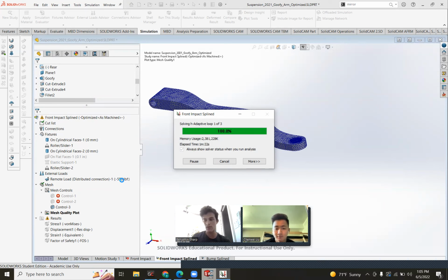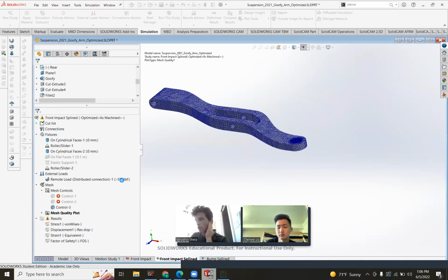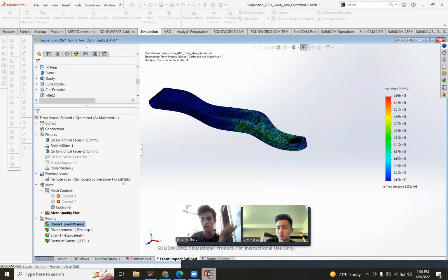Well, the reason it does not matter whether SolidWorks tells you there's like 1 or 2 failing elements in the bearing cup is because there's just a lot of tiny edges in there, but also because it tells us that the bearing cups should have been failing in the wafers every year for the entire history of Baja, based on the designs we've been using and the loads that we use in FEA, but they never have. So either SolidWorks does a bad job of FEA in the wafers, I think that's what it is, or the loads we've been using are like 3-4 times higher than they should be, and that's the issue.